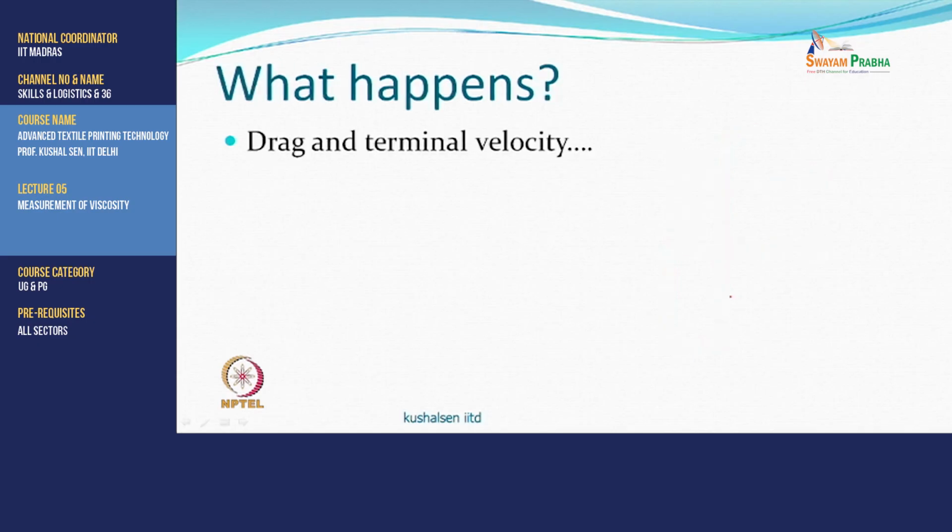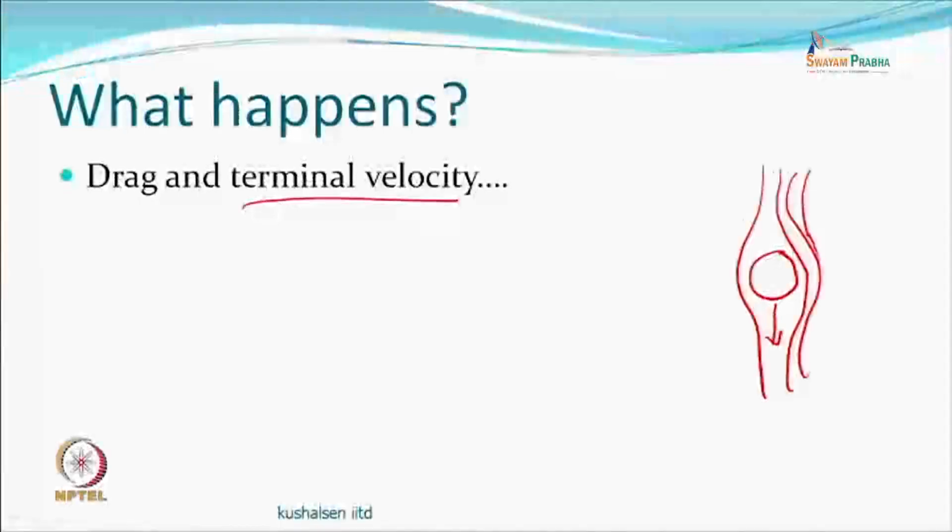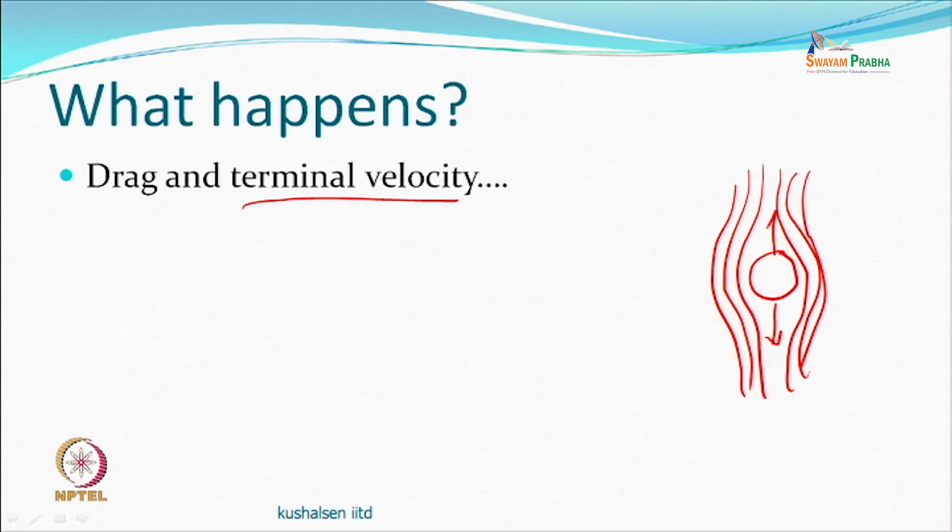Why this is important is there is a term which is terminal velocity. If this is a ball which wants to go down, let us say, there are streams all around the ball as it keeps moving. So gravity is going to pull it down, but there is a drag force because of viscosity, and buoyancy, which will in some sense keep it up.